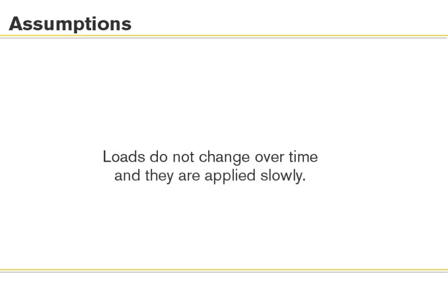The third assumption we make in Express is that loads must be static. This means that we assume loads do not change over time and that they're applied slowly. Most structural loads can be represented as static loads, including forces and pressures. Time-dependent loads, such as vibration from shaker tables and engines or drop testing, would require dynamic analysis available in the more advanced SOLIDWORKS Simulation products.